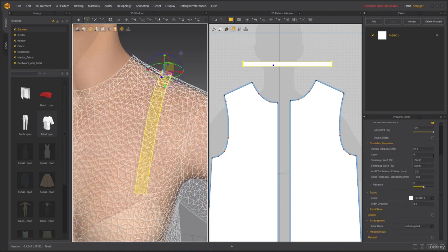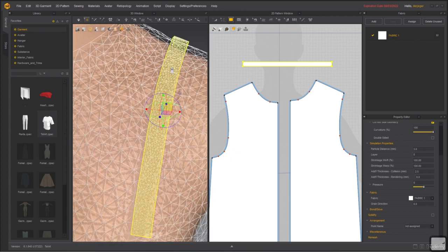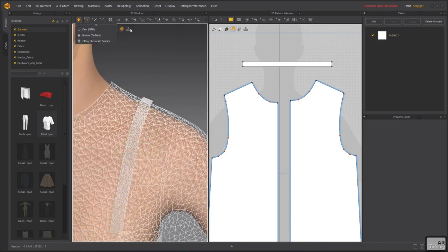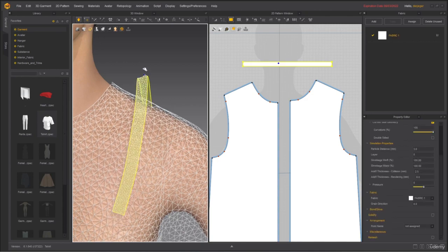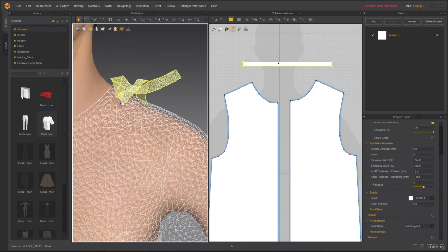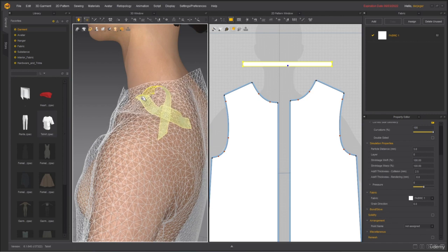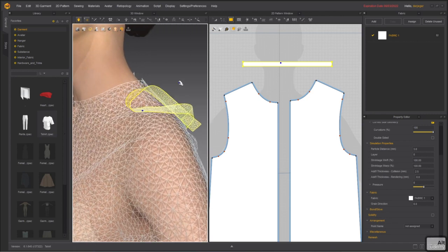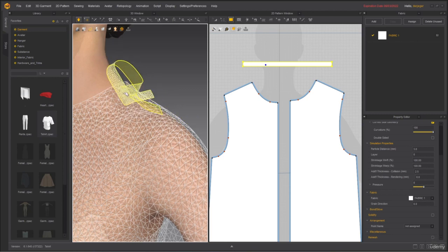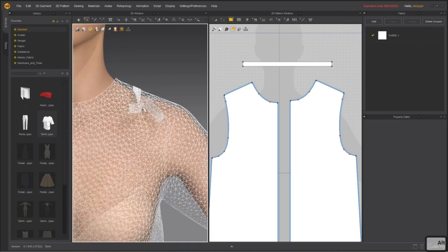So for small pieces, you can actually go really small, like 3, for instance, and then you can see that we get super fine detail, and that's going to allow us to get a little bit more details and effects out of this little piece right here. So when you're working with really big pieces, you can have a larger particle distance, and when you're working with little small pieces like this one, you can have a lower particle distance. That's usually the way to go.